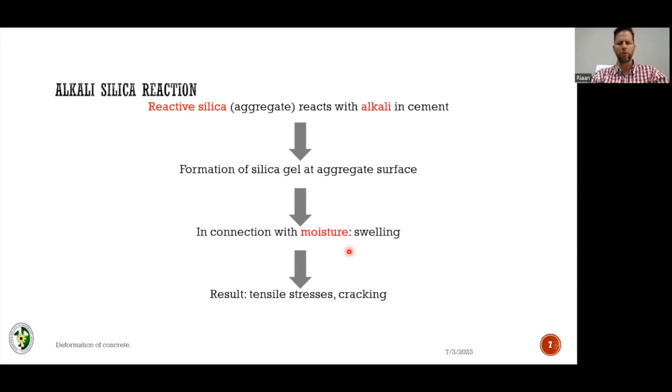Now, if you remember from last week, we said that your concrete uses about 40 liters to 60 liters of the water that you've given it in your mix to create gel crystals, your CSH gel crystal, and also some calcium hydroxide. It's not using all the water. So eventually, you might say that the term of concrete drying out might apply. Your concrete will lose its moisture over time. But some of the moisture in there stays there for a very long time.